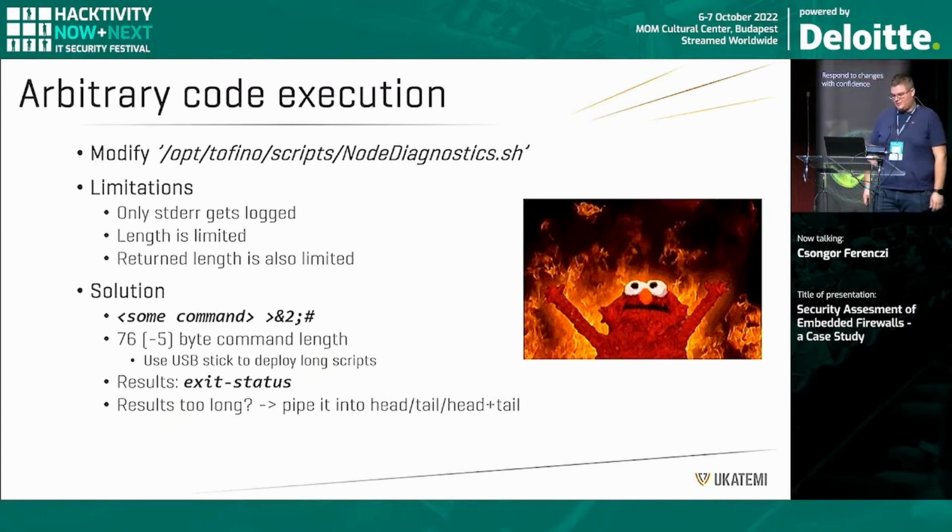So that's what we did. We inserted a pen drive and dumped the file system. To achieve this, first we had to figure out how the FPGA isolated the USB port from the CPU, because nothing was showing up in lsusb. However, after finding the relevant script and undoing the magic, we had no more obstacles ahead of us.